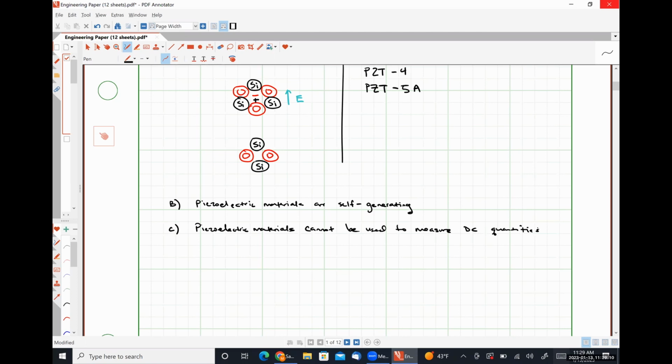Those were all piezo speakers. And so you applied a square wave voltage to them. So either voltage on, voltage off at a specific frequency, and the output you heard was that crystal resonating and pushing air through that little circular aperture in the middle of the housing, generating sound.